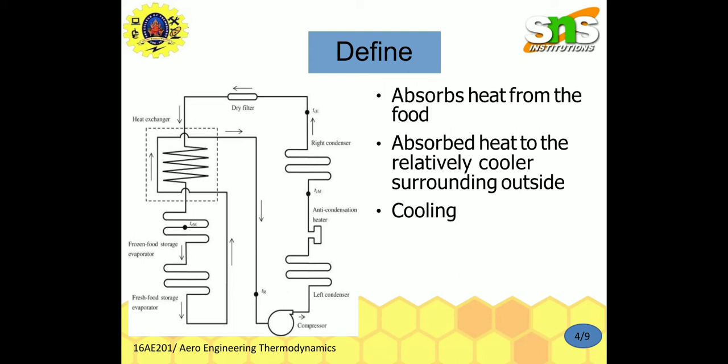Components corresponding to the condenser and evaporator in a vapor compression cycle are the hot and cold gas-to-gas heat exchangers. For given extreme temperatures, a gas cycle may be less efficient than a vapor compression cycle because the gas cycle works on the reverse Brayton cycle instead of the reverse Rankine cycle, such that the working fluid never receives or rejects heat at a constant temperature.